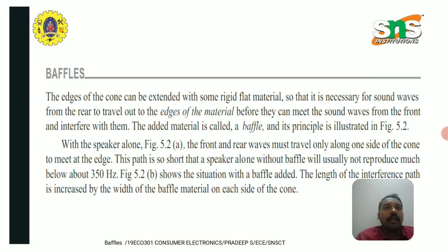The edges of the cone can be extended with some rigid flat material so that it is necessary for sound waves from the rear to travel out to the edges of the material before they can meet the sound wave from the front and interfere with them. The added material is called a baffle. With the speaker alone, the front and rear waves must travel along one side of the cone to meet at the edge. This path is so short that a speaker alone without a baffle will usually not reproduce much below 350 Hz.